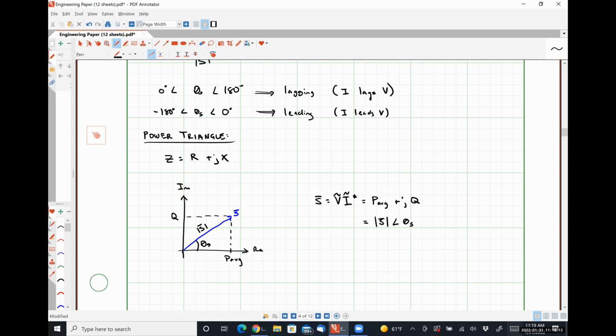so do you guys know anything about the concept of ampacity? Probably not, okay. Ampacity is the technical term for how much current a wire can safely carry before it melts its insulation, which then could potentially cause short circuits, fires, and all that kind of good stuff.